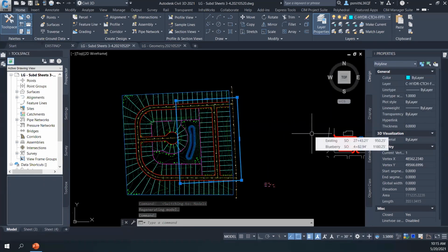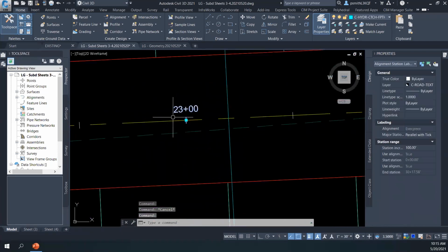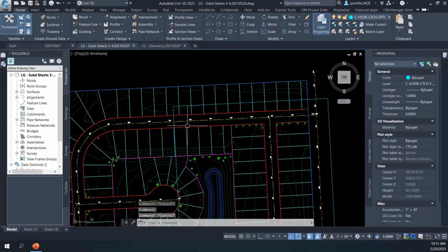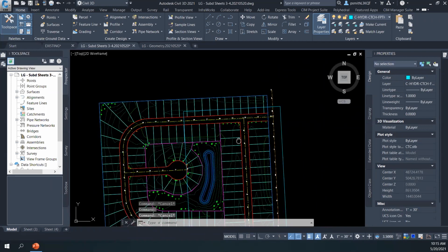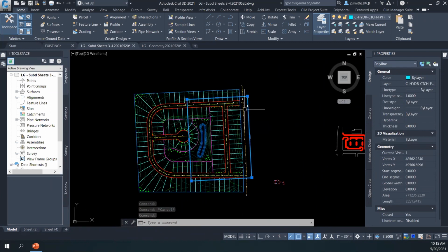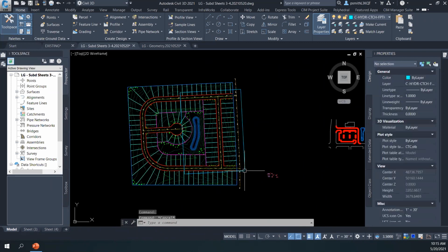No more guessing on where your match lines would be by, I don't know, however you do it with your stations or whatever. Just get the exact location of where your match lines are going to be. Also, it helps you lay out, if all your viewports are the same size, you can just lay out every location of where you want your viewports to be located as well.